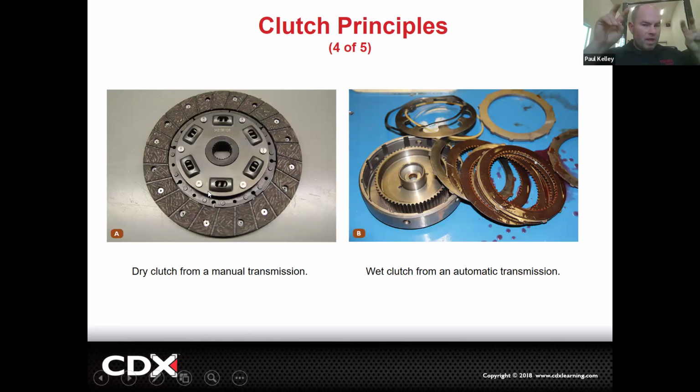on an automatic transmission. If it's a dual clutch transmission, it'll actually have a disc like this on some of them. There will be a couple different shafts it's got to connect to, but there will actually be a three-phase AC motor to engage and disengage this. And the computer controls that. The computer controls the 12 volts and ground to apply or release that clutch, right from the computer, so the driver doesn't even know.